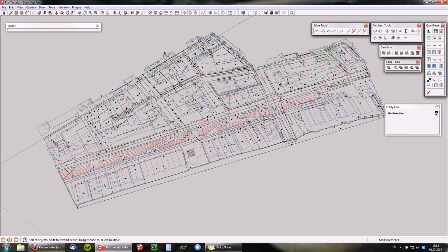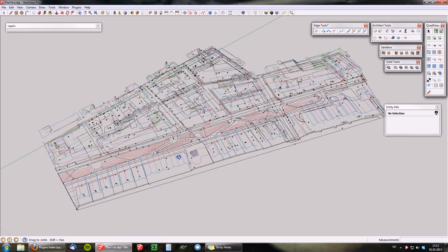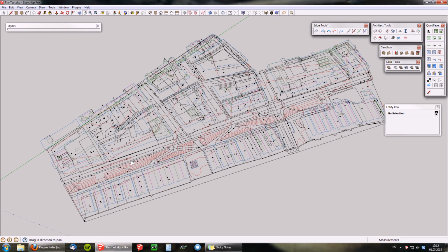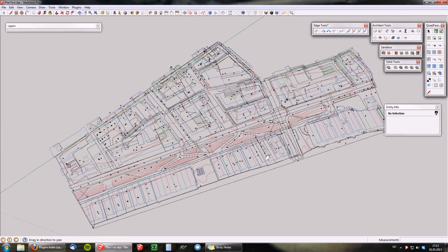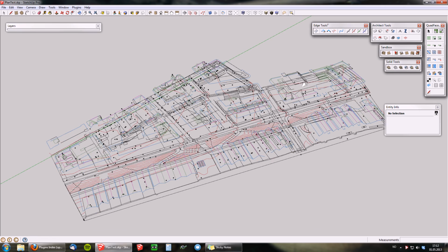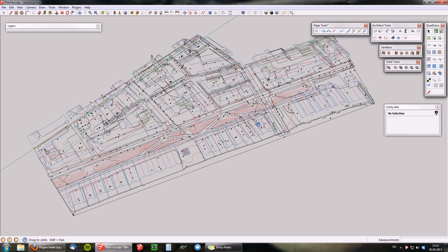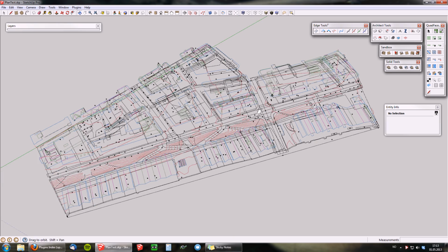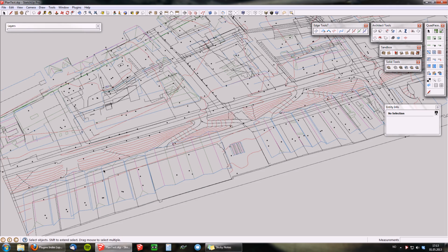Generating stepped terrains in SketchUp is a little bit more labor intensive, since you have to make sure that each contour curve is properly connected before you can push pull each of the levels. Normally the biggest problem I found with the kind of maps I get when I build my terrains is that they're not always connected properly.